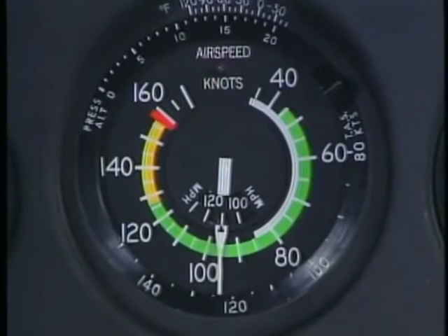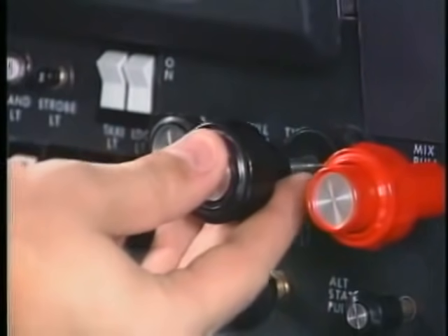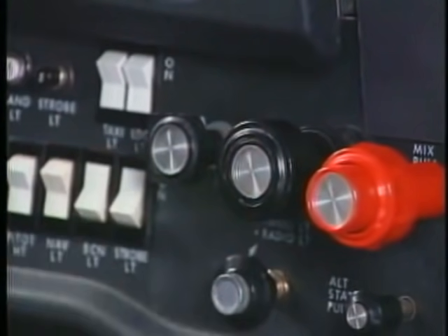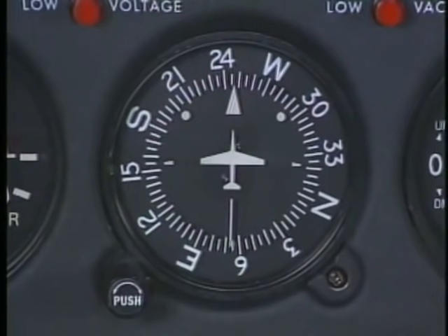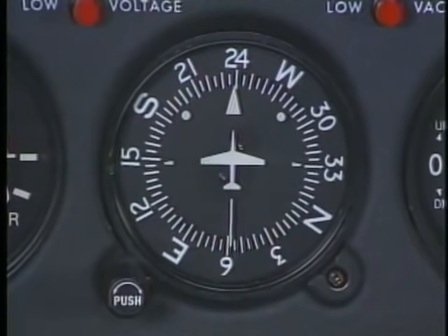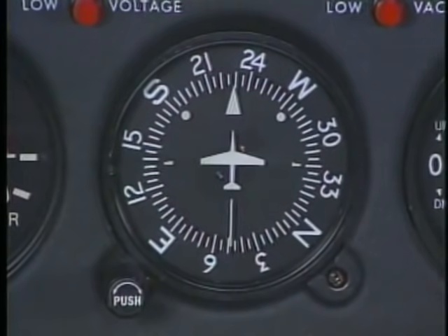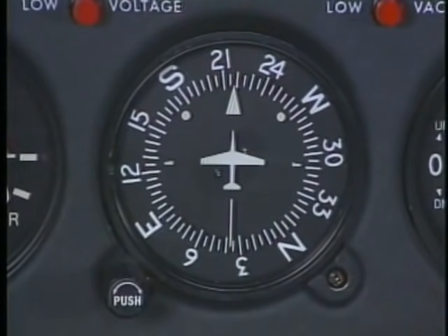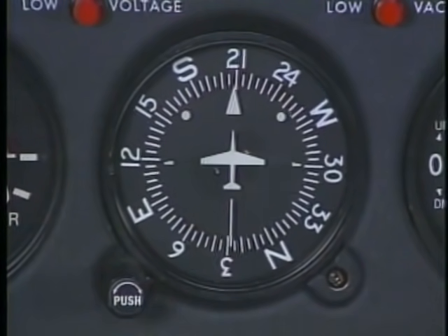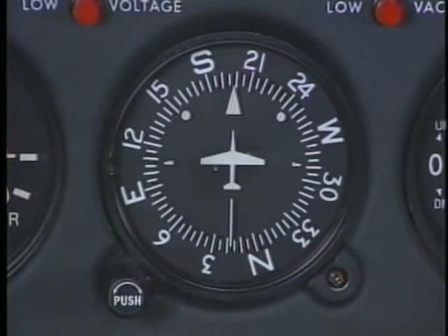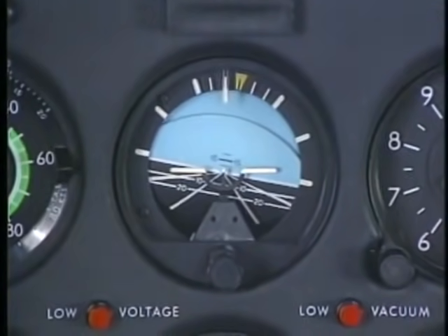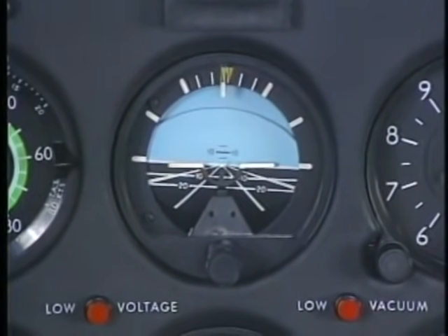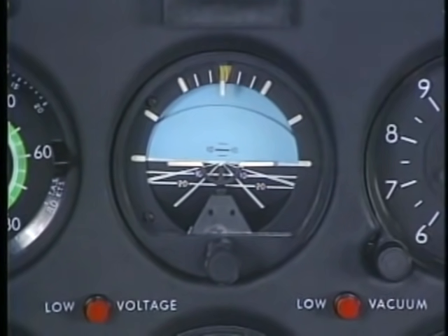Since an airplane tends to slow down during a steep turn, you need to increase power to maintain airspeed. Remember to lead the rollout by 1/2 the bank angle. For example, if you're turning to 180 with a bank of 40 degrees, start your rollout at 200 degrees. As you begin the rollout, you need to reduce the pitch attitude and power to maintain level flight. Then retrim the aircraft.